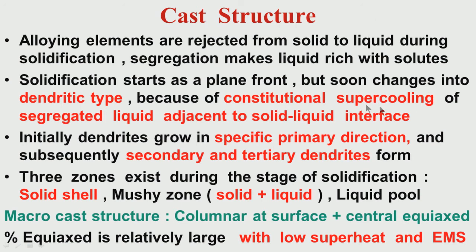It means the temperature of the liquid just in front of the solid-liquid front is getting cooled because of segregation. So, this is called constitutional supercooling.